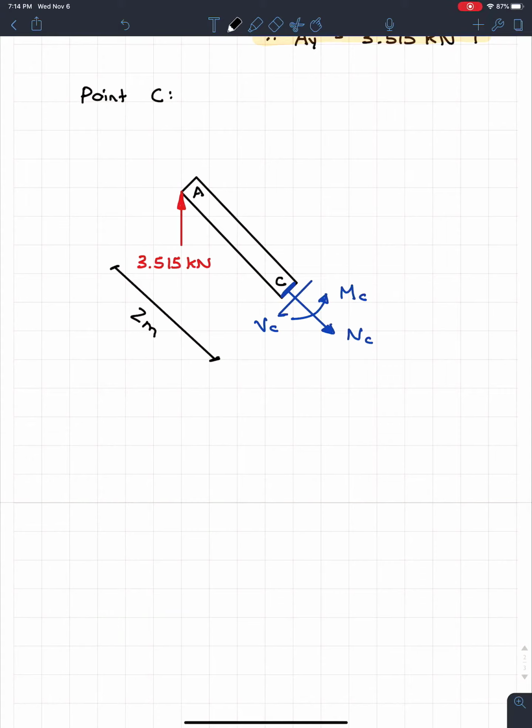So if I take my axis and make this my new axis, the X is going to run parallel with the beam like this, and I'm going to call this x prime, and I'm going to call this one y prime. Well, now, if we rotate everything, we'll see that this is actually the exact same as a normal beam with just a diagonal load. And this diagonal load, we already know, is acting at 45 degrees. So now our lives just became a lot easier in this case.